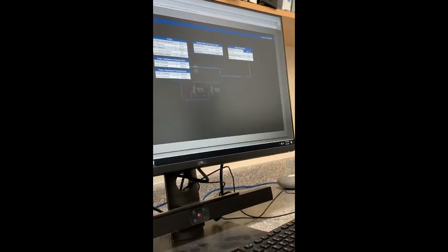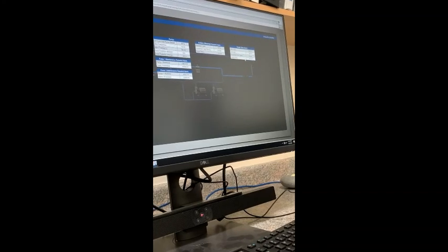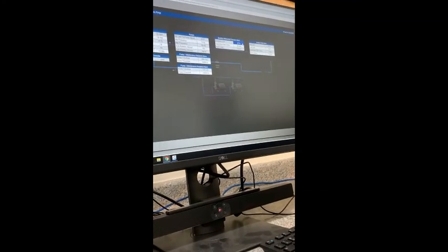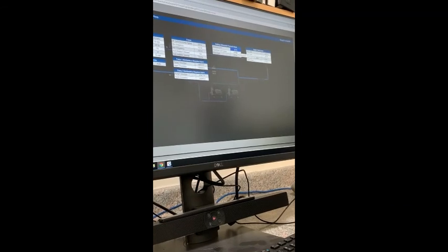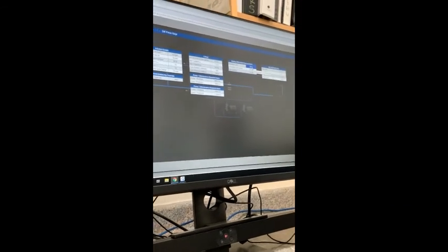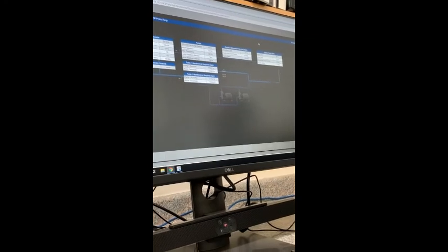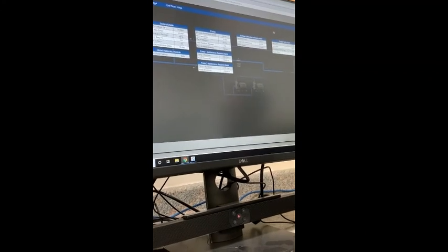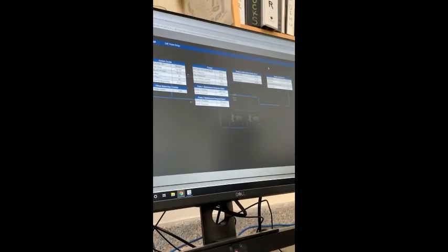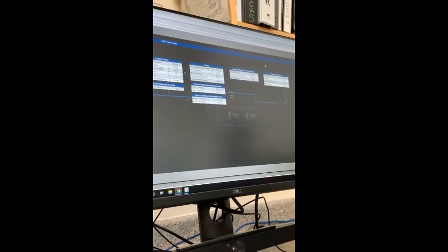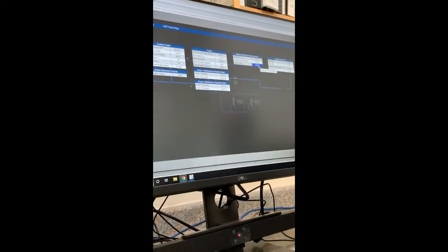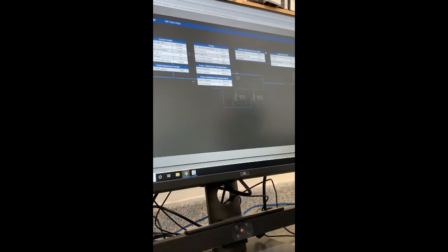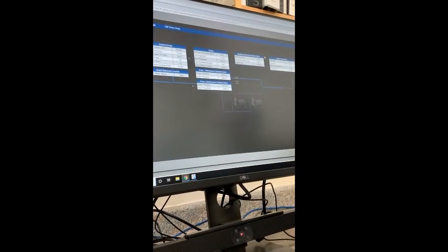So you'll see like the supply temperature high-low limit, the building differential pressure alarm. So this is based off a deviation. So this is set for 20%. So if the pumps were running and we were 25% under our set point right now, our 5, so if we were at 3.7, because 25% of 5 is 1.25, so if we're under that for 20 minutes, it would go into alarm. Right. Or if we were over, it would then go into alarm.